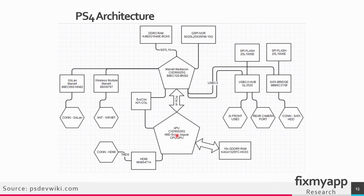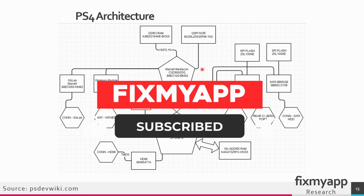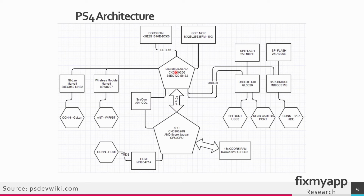So the APU sends its graphical data to the HDMI encoder IC, and from there it will go to the HDMI port. So this HDMI port is not connected to the Southbridge IC. It will go from the APU to the HDMI encoder IC, and from there it will go to the HDMI connector. You can see that the Southbridge is the center of most input-output operations that are done on the console, and it will communicate with the APU. So when the Southbridge is not working, most of the time you have a no power condition. So this is a global overview about the architecture of the PlayStation 4.